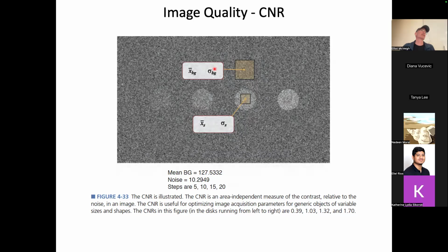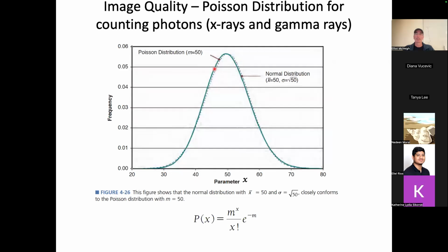If you can't find something that's constant, if you have two images of the same thing, you can subtract them. And the only thing that should be left is sigma, right? Because you've taken all the features out, and you should just have an image, a noise field that is sigma. So that's another trick you can use, but you still need two images to do that.